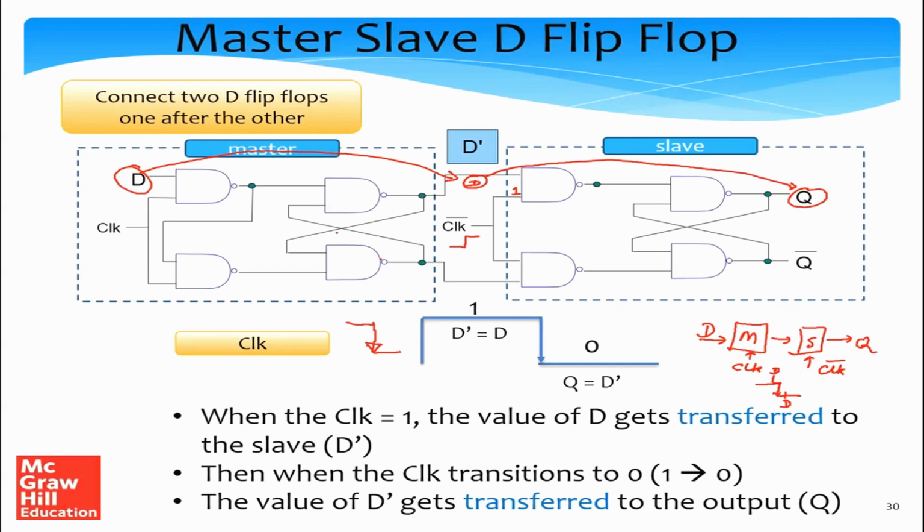So what is the advantage of having such a structure, a master slave D flip-flop? Well, the advantage is like this. It'll be clearer actually in chapter 9, but I can give a little bit of a preview. Typically, while designing a large processor, we will have to save some values in D flip-flops. So let me call this an FF. And then at the beginning of a clock cycle, which means at a negative edge, the data will come at the outputs of the set of flip-flops.